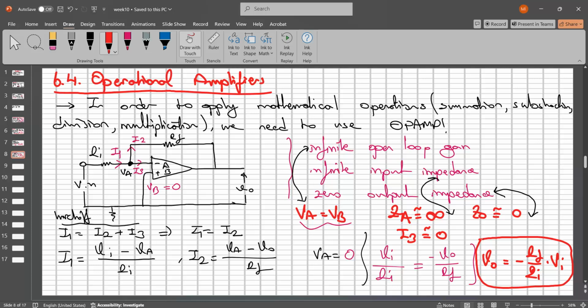Which type of amplifier can be used in this case? This is amplify, right? With a proportional one. And so this is the proportional op-amp. We multiply the input signal with another one, the R coefficients, RF divided by RI, right? Right? Any question about that? Any question? No question? Everyone gets everything about the op-amp right now?